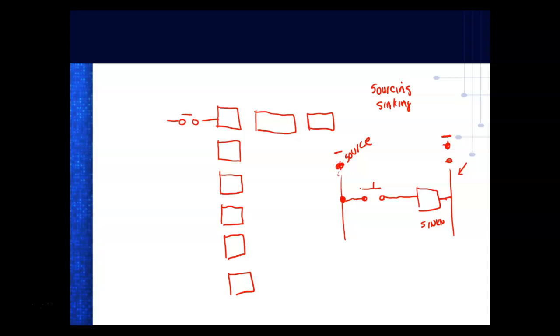So what I would have to do, so my battery, my power supply would be connected like this. Okay, and this would come into this side. This is internal, right? And then I would have to take the plus out, and I would have to run it out to my switch. So a syncing input port would require a sourcing input device. Does this make sense? Yes or no?